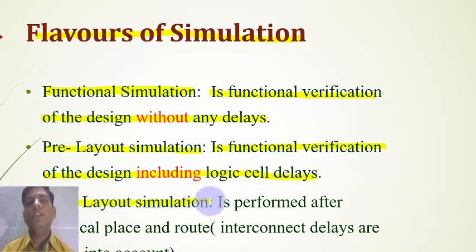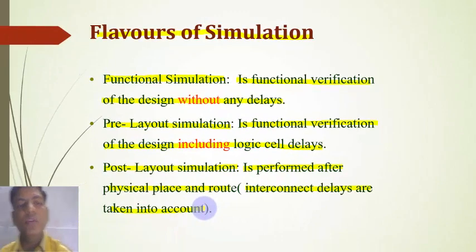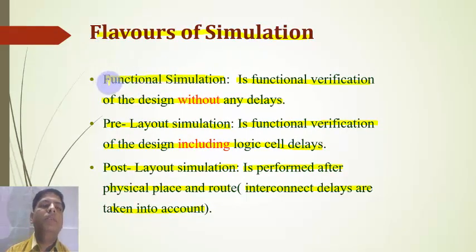Post layout simulation is performed after the physical place and route, which means interconnect delays are taken into account. So the flavors of simulation are functional simulation, pre-layout simulation and post-layout simulation.